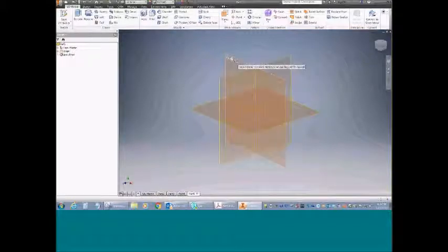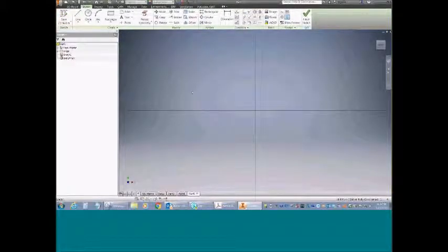So for this one, I wouldn't lead them through the entire thing by any stretch of the imagination. I would just try and give them some pointers and some suggestions on how they might accomplish this. The main body section was an L, and I would give them some different possibilities: instead of drawing all the lines to make up that L, I could potentially just do 2 rectangles, and I could get my L shape out of those 2 rectangles really rather quickly, so that all I have to do is apply some dimensions here.